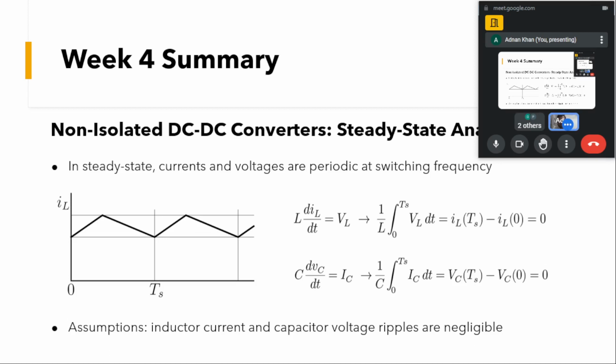If this balance isn't there, if the inductor stores that amount of energy and doesn't give it back, there will be a buildup of stored energy, and the current will gradually rise. The inductor current will increase to a value that will damage our device or circuit.